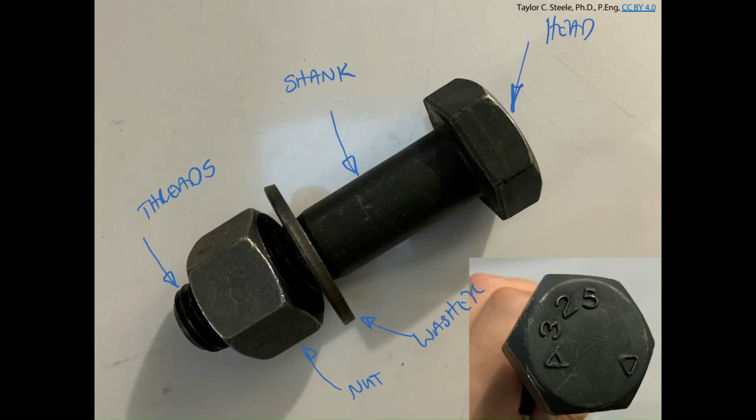And then the bolt itself has a few different components. The bolt has the threads, which you spin the nut onto. The bolt has the shank, which is where the area is not reduced to account for the fact that we've got threads. Then we've got the head of the structural bolt. One of the things that makes structural bolts different from other mechanical bolts is that the hex head is quite a bit heavier. It's usually about 1/8 of an inch to 1/4 of an inch bigger than a typical mechanical bolt for the same diameter of the actual bolt itself.